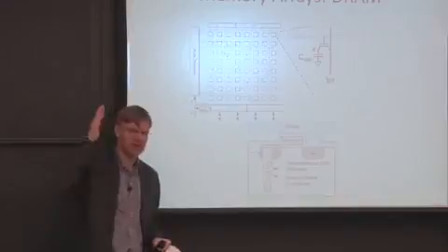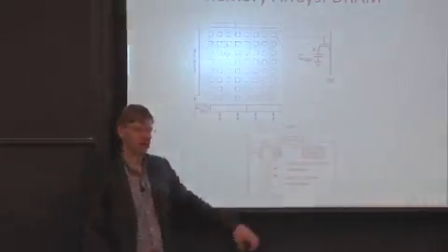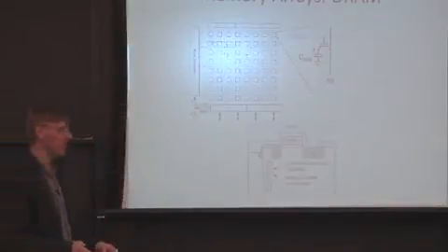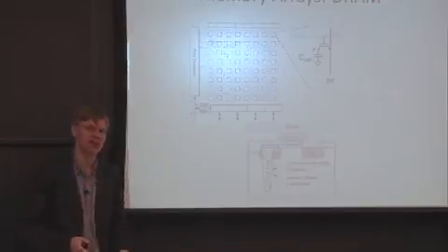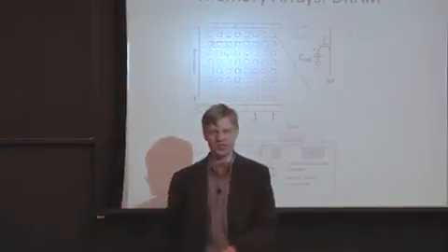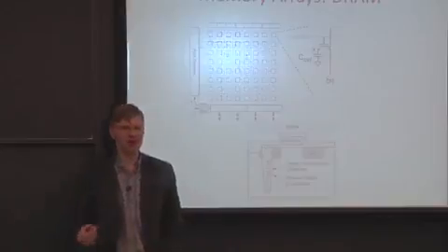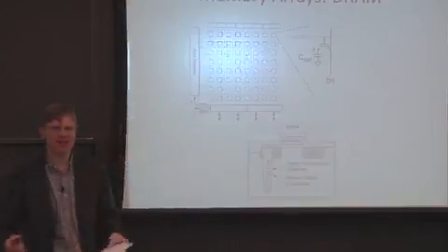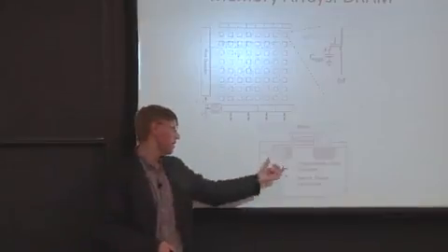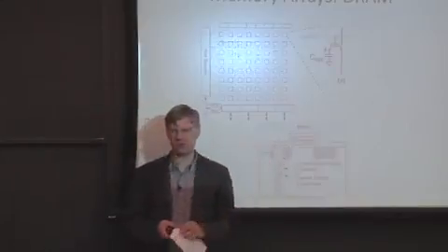And the reason we do this is because we want to see that the actual capacitor is very long, or very deep into this. And one thing I wanted to point out is this is typically really hard to go build on your standard CMOS process. So this is hard to go build on something like a logic process. You have to go build this, let's say, in a special DRAM-only manufacturing process. So it's sometimes hard to mix that. There are some technologies which allow you to mix them, but when you do that, people haven't really designed ways to make the DRAM cells as small.